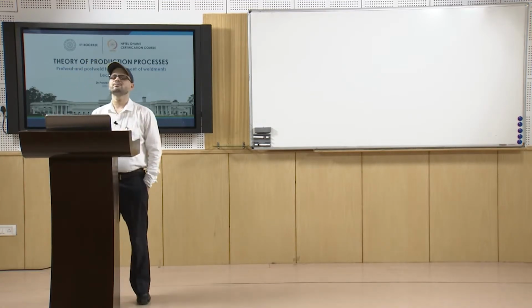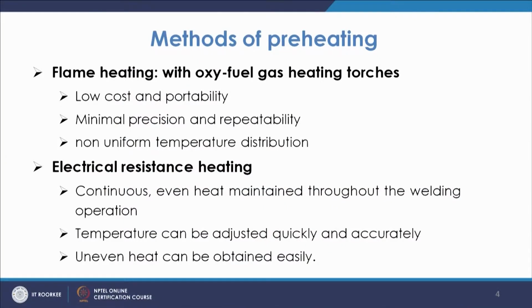Now, the method of preheating. When we talk about how we can do preheating, you may do it with a flame. You can use oxy fuel gas heating torches.